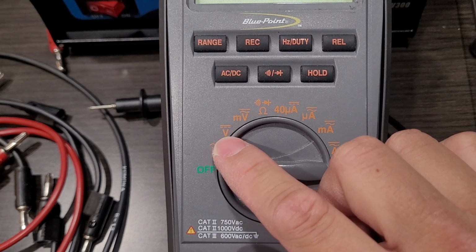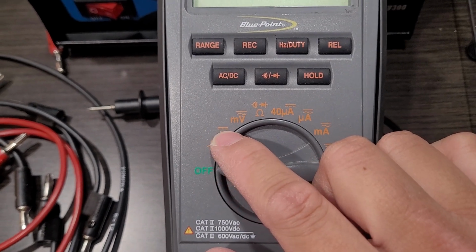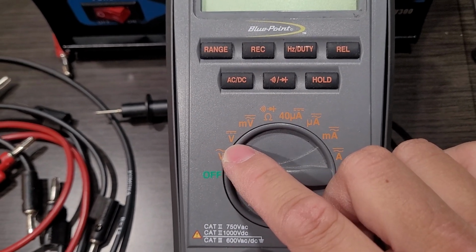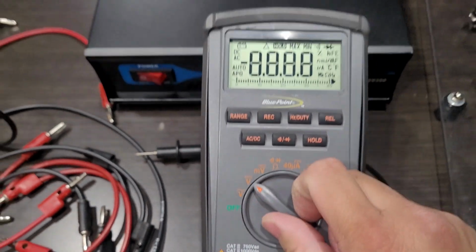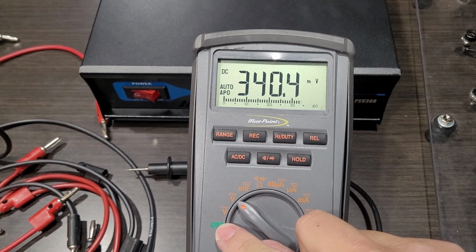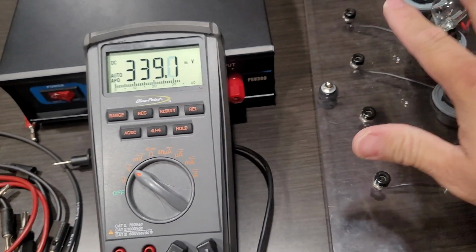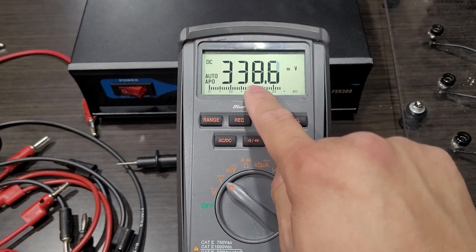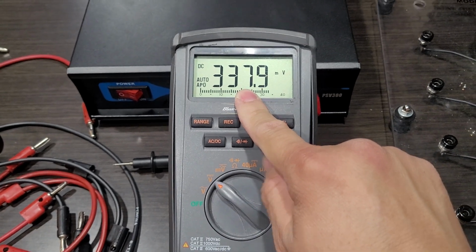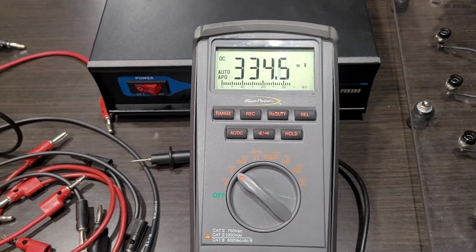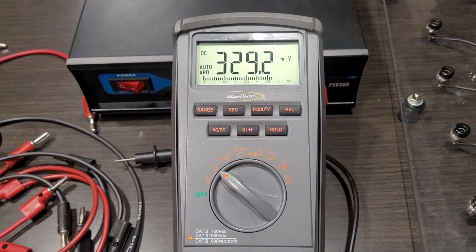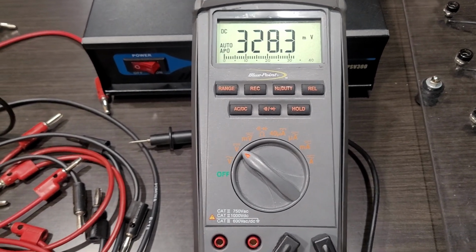So that way on top of the V here, you'll see a flat line, okay? That represents digital, okay? So make sure you turn it to that setting. Otherwise, if you turn to the volts AC and you start putting your test leads on there, it will not give you a good reading. And students, most of the time, when they do that, they'll write down the wrong readings on their labs, or they'll interpret it wrong, assuming there's something wrong with the circuit, okay?